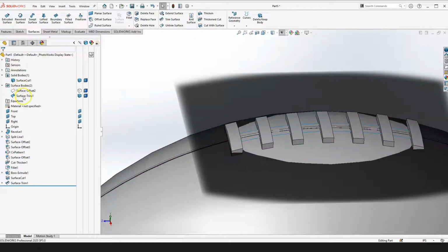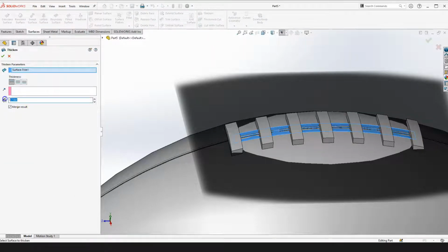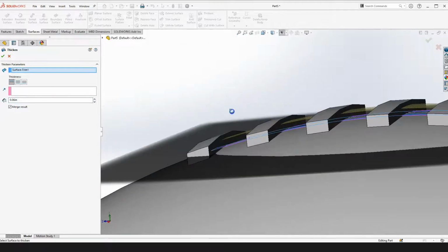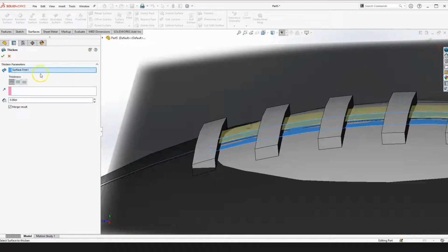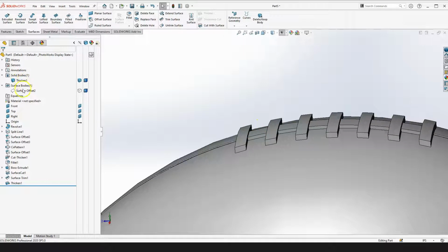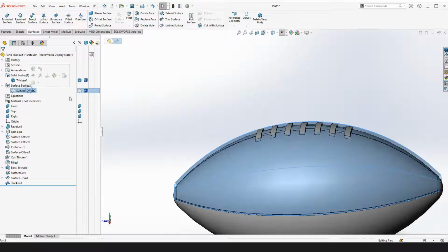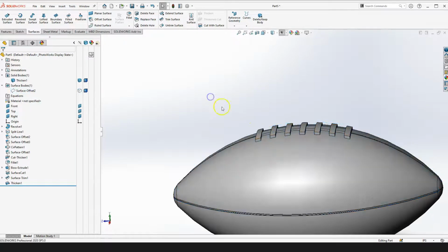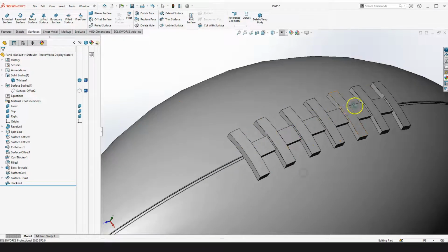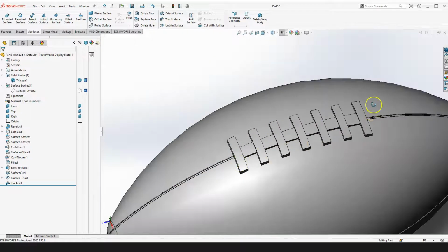So click on that surface you just created, click on thicken, and give it like 0.06, and look at what direction that thing is going. Yep, perfect there, and press OK. Yeah, perfect. Now I got rid of that surface from here. Now that was merged into that one solid body there. So the only thing I have left is that one surface offset that I had used to cut the grip feature there. So now here it's just a matter of giving a radius to these features here.